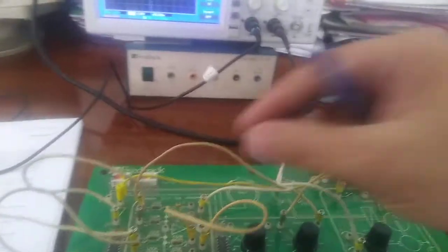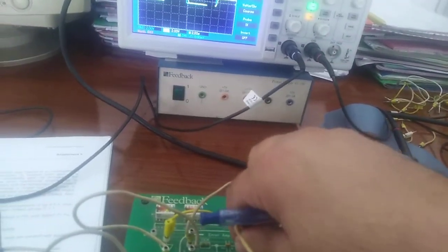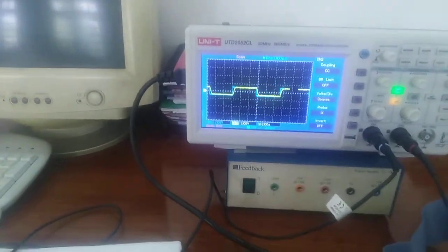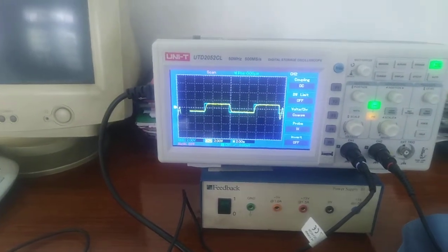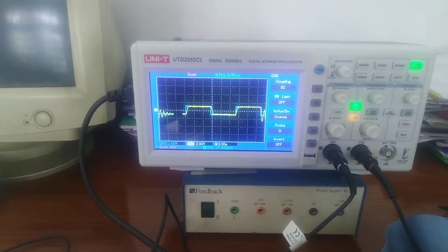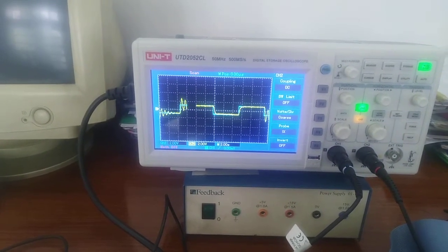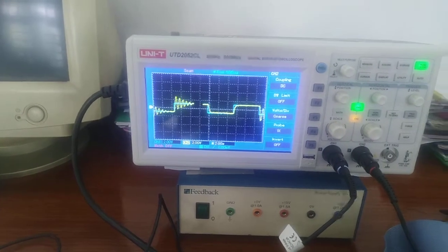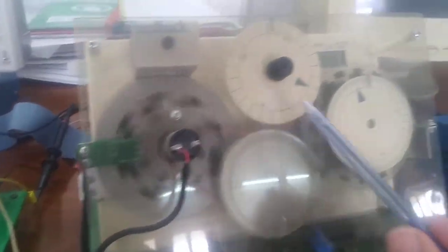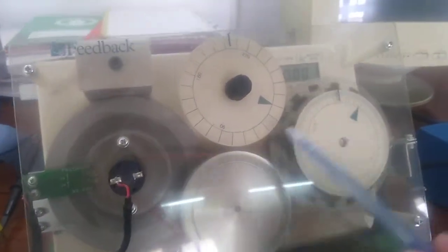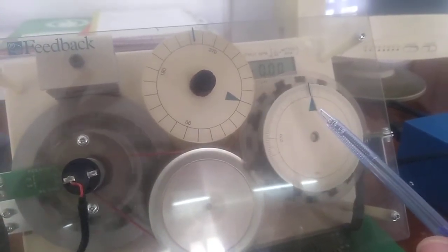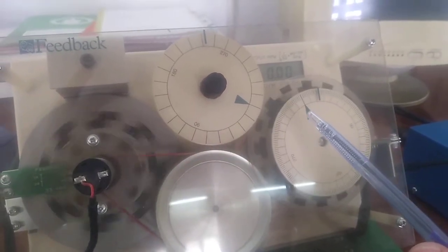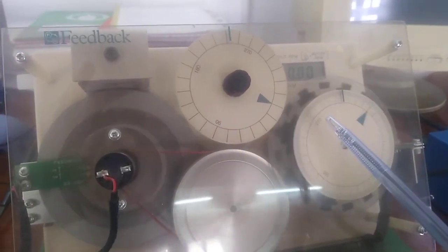Now, further increasing the gain to 10, you can see here again. Let me decrease the velocity feedback to 0. So you can see here there are transients in the square wave, right? This is the response of the DC motor, and again you can see here this is the aluminum disc, and the shaft is connected by gear. This is the output rotary potentiometer. This is the shaft position, and you can see here the transients and oscillation in the motor.